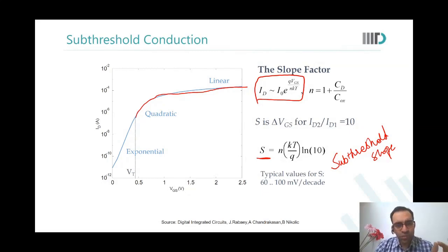Yes, sir. So these are PN junctions, is it not? Yes, sir, but they won't be evident at low voltage. They are reverse biased, to be precise. But is there no reverse bias current? They're always reverse biased. You do not ever want to have those PN junctions forward biased. Yes, sir. But there is a reverse bias current. Okay, sir, I do understand that. But what is this current exactly, sir? Current flow between source and drain, or drain and body?